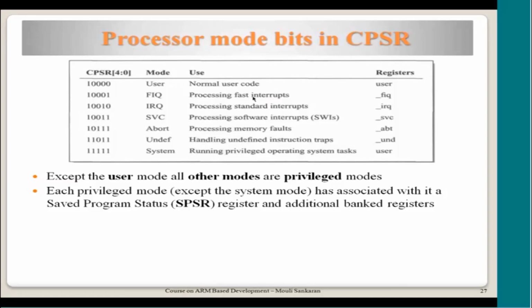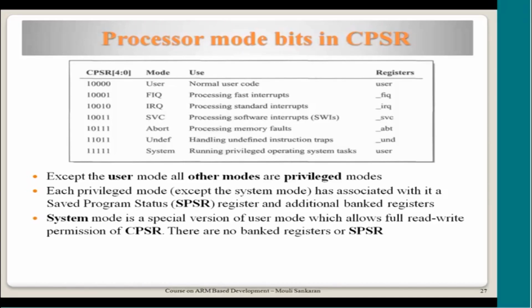Now, after the interrupt routine, when you come back, you will not get the same state of what you had prior to the interrupt. So, to achieve that, what ARM has done is it has made visible another register when they are entering into this mode, and automatically the hardware takes care of copying it. I am telling you this right now just to give you an idea of why SPSR is needed, but we will talk about it later on in detail.